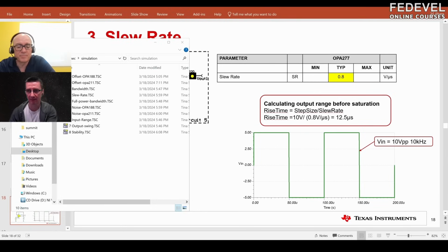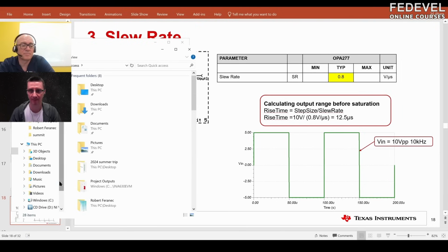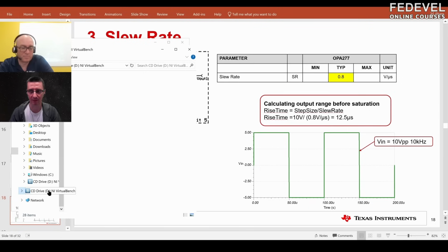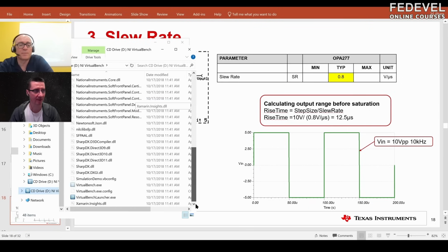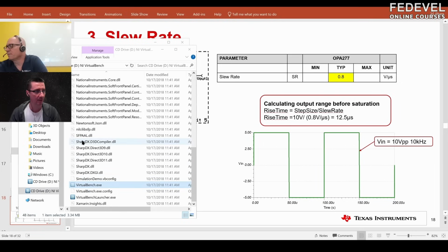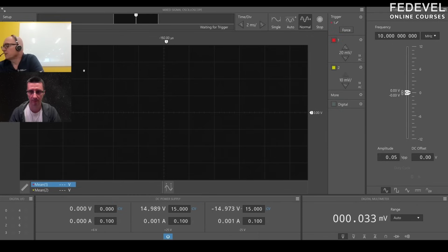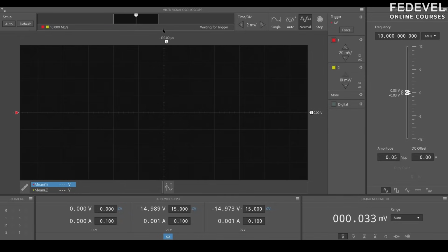So with this board, you can measure all these basic parameters of any op amp which you would like to use in your board. Of course, the equipment itself is a limitation. It's all-in-one equipment, so it's not optimized for extreme accuracy. And then the circuits themselves are other limitations. Even with high-end equipment, oftentimes you have to use special configurations.